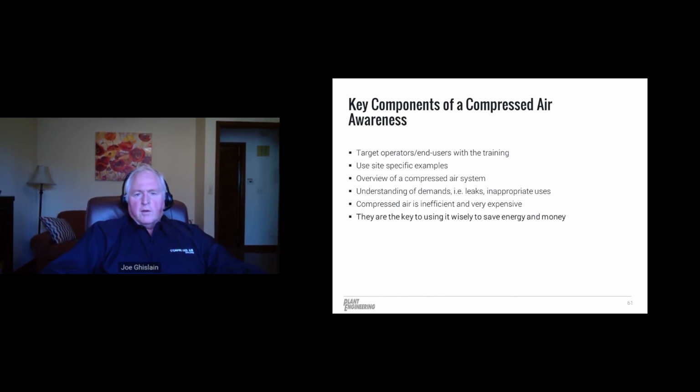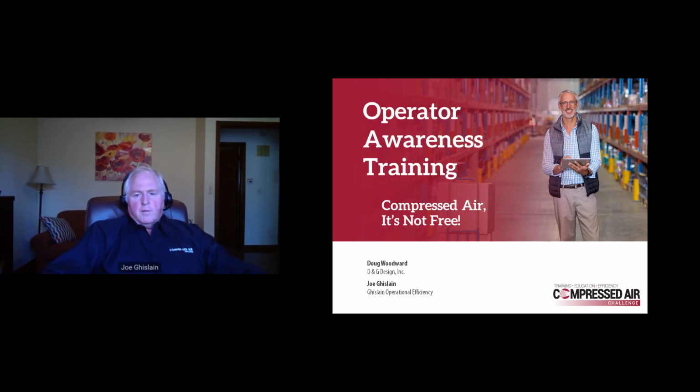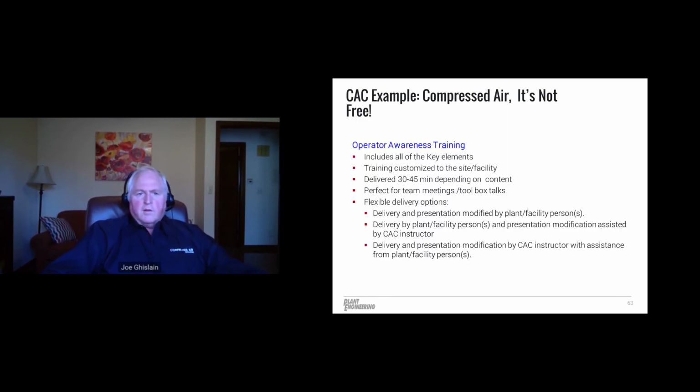And this is a key component. So you want to have a compressed air awareness program that targets the operators, end users, and the maintenance personnel. You want to use site-specific examples. You want to make sure that you have an overview of the system so they understand it. They understand demands, leaks, inappropriate uses. They can see them in their plant. You want to let them know the compressed air is inefficient and very expensive. They are the keys to it being used wisely and saving energy and money. So they're the ones that need to be part of it. You can develop your own compressed air challenge. I mentioned we put together one as well.